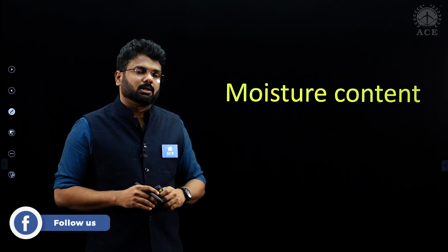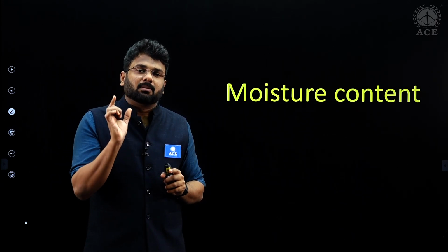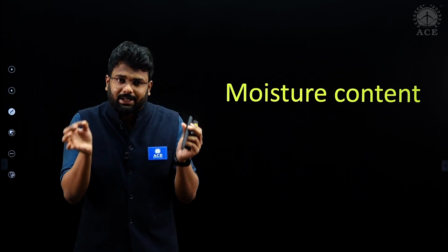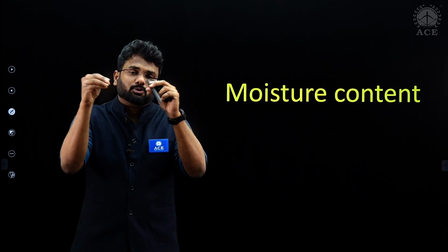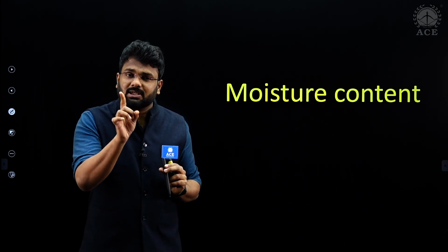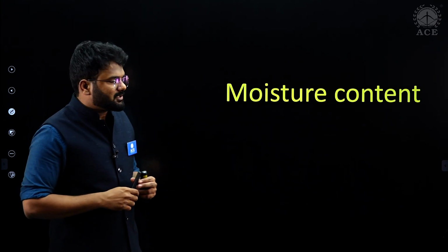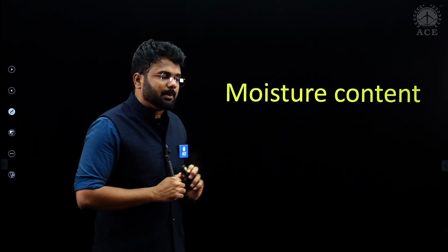One more important parameter from your site point of view is the moisture content in your timber section. It should be perfect moisture content. If it is not right, then your section will absorb moisture from the outside atmosphere and change dimension. This will induce unnecessary stresses in your structure. So that is why moisture content becomes important.